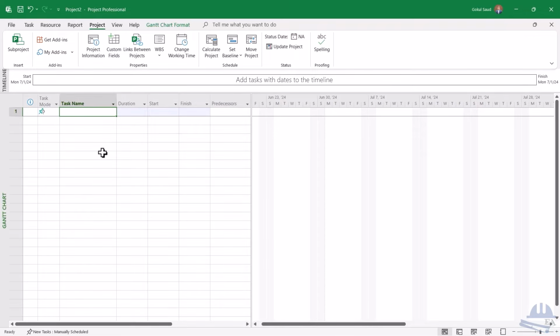Once you have all the drawings and things, you study the drawings. After that, you create a whole movie in your mind of how you're going to start the task, how you're going to start the project. So you have to imagine that first thing you'll set up the camps, that is the mobilization part, right? Then you will do the surveying and layout things. Then you will do the excavation. Then you will finish the foundation. Then you will do the tie beam, then the ground floor columns, then the beam and the slab, then the first floor columns, beam and the slab.